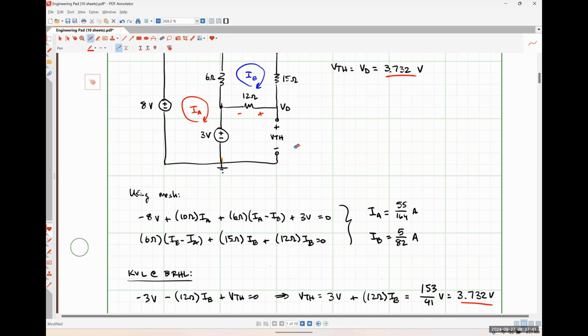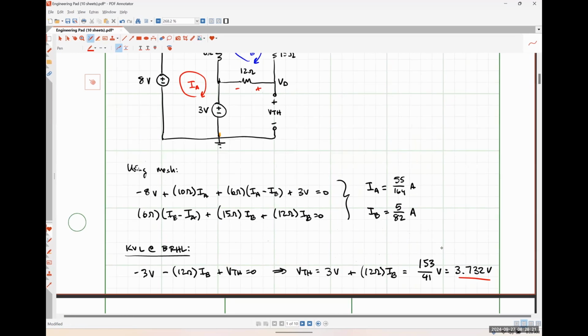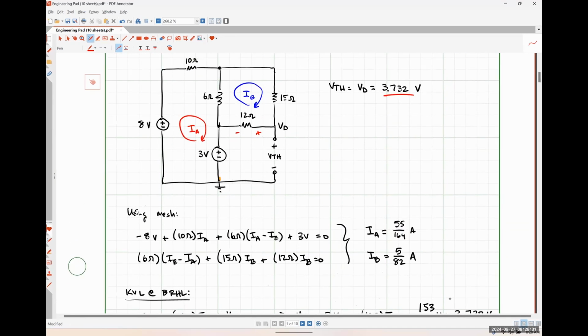So what we're doing is we're finding this open circuit voltage, and then we're going to use that voltage along with the Thevenin resistance to construct an electrically equivalent circuit that will make calculations easy, if we're interested in things like power and all of that kind of good stuff, okay? But this can also be used as a circuit analysis tool. Just for the sake of argument, if I have a complicated network that I can disconnect and leave behind a 2-terminal network, I can just find the Thevenin equivalent of that and use that to represent the big ugly thing I don't want to deal with. We do that a whole lot in higher level electrical engineering classes, and this class will do it every now and then. But anyway, all right, so finding RTH.